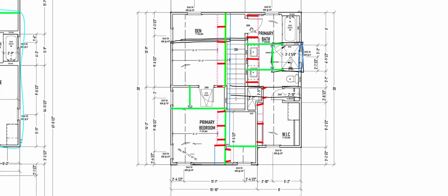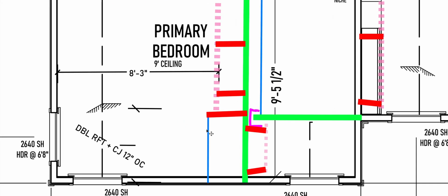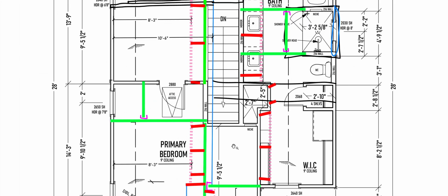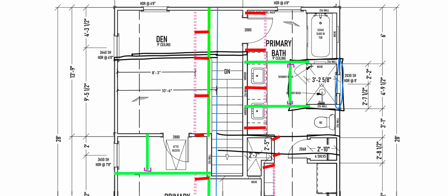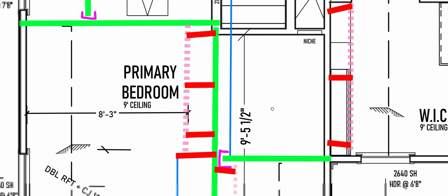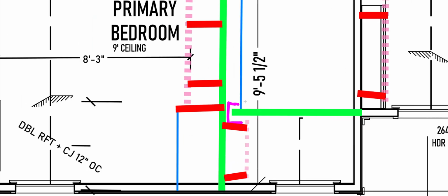Okay, so now what do I know? I know my rafters have been all supported properly. So not only are my rafters good to go, and this ridge was taken care of here, but I need to take care of this blue ridge now. This one coming all the way down here. And that's not going to be too hard, I think. Yeah, it's not going to be too hard. So this ridge, I want to put it on this beam. So this beam is almost directly below this ridge, and I've got a bunch of height to work with here. So I know that I'm clear.